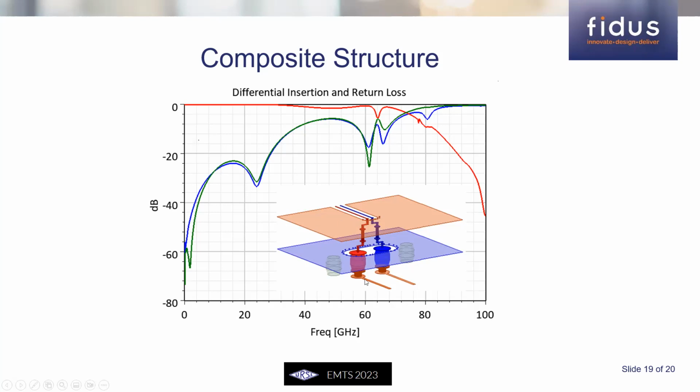If we reduce the pitch of the BGA, like some of the packages that do the very high speed PAM4 200 plus gigabits, they're likely to use the 0.5 mm pitch BGA. This response will improve slightly, and it can be improved to a slightly higher frequency. But essentially, the limitations come from the BGA balls.